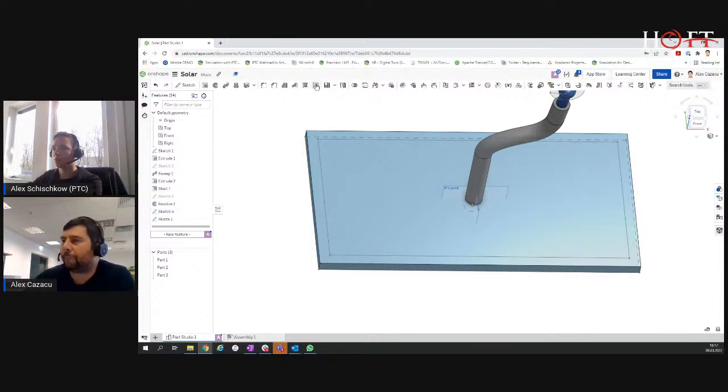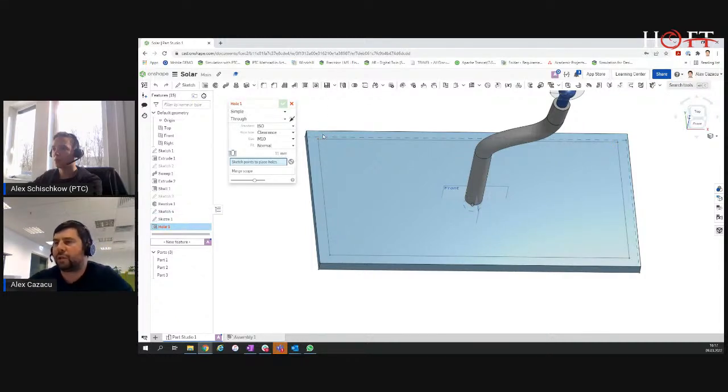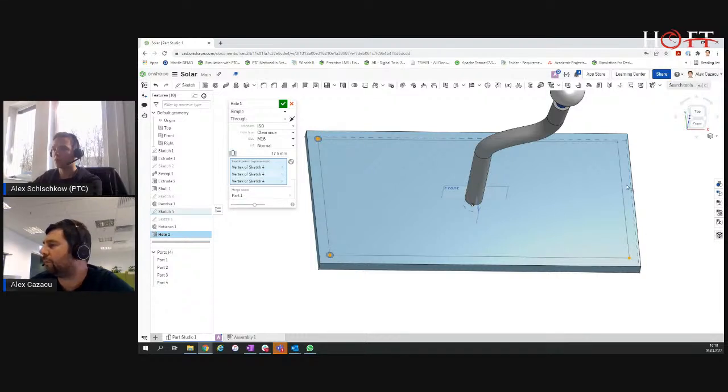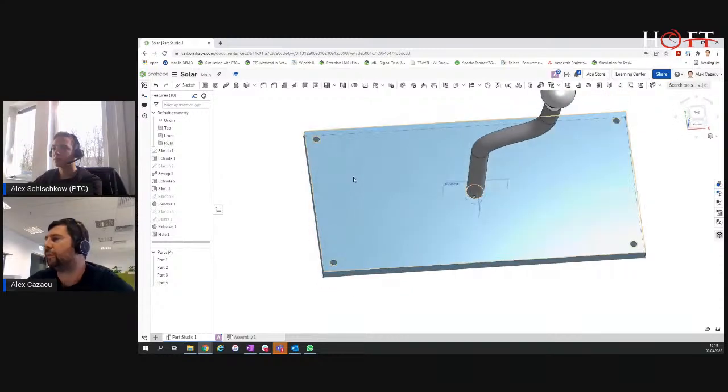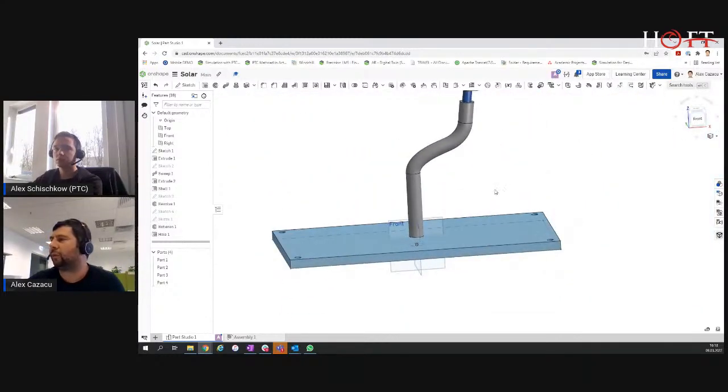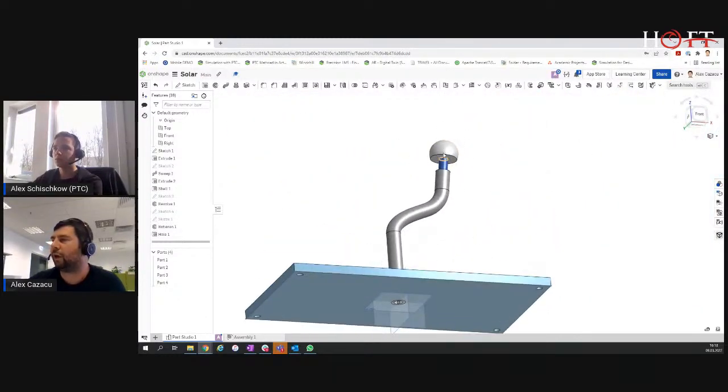Okay, this new sketch will allow me to use the 4 points on the corners as holes, center points, starting points. So the holes will be simple, will be through. I can also have a counter bore or a countersink. I can use pretty much any standard I want. And I'm going for, let's go for metric 16. I'll just click on the corners, and I have all my holes prepared. You can see that my colleague already created a new part, so we have a new part here.